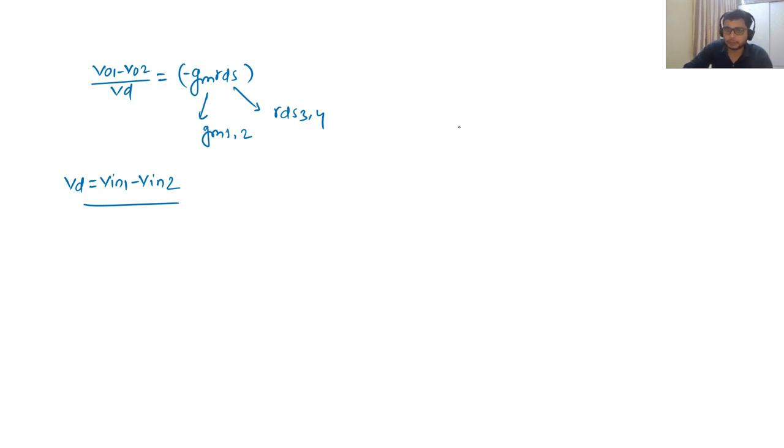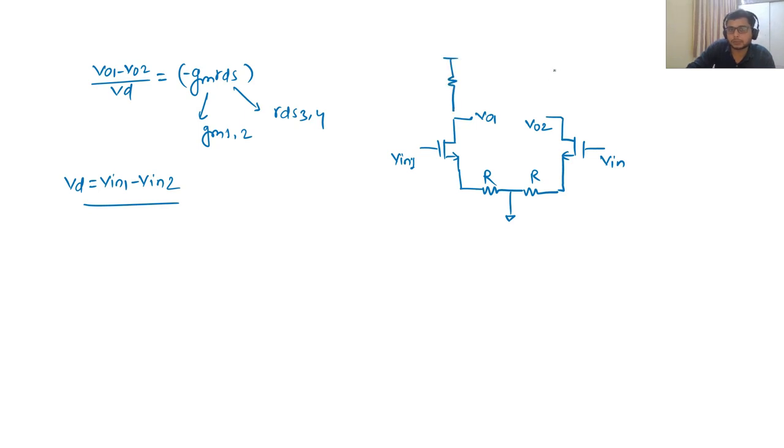And for the second circuit, there is no difference. I'm just drawing the part AC wise. So this is R. The two R I have split like this, and from the symmetry viewpoint, I can take the virtual short, and this is the way. So what is above that, what is lower than that, you can see. I can calculate V out 1 here, I can calculate V out 2. So from the AC viewpoint our circuits are the same. Here some resistance, here some resistance due to the current sources. So AC wise both circuits are the same.